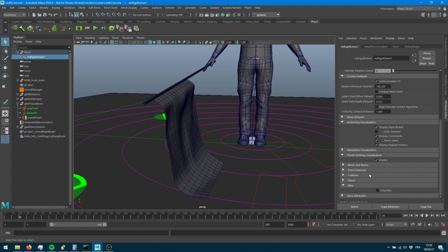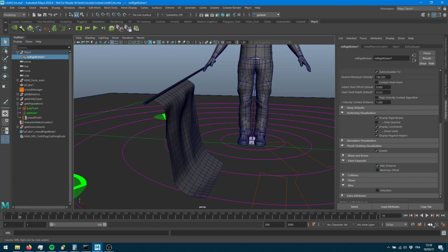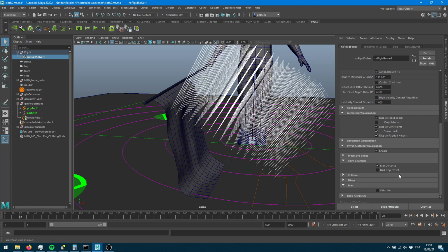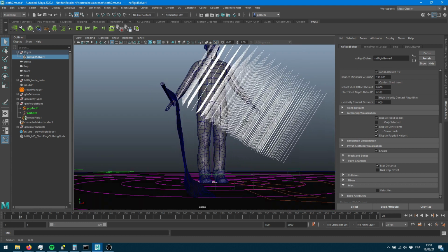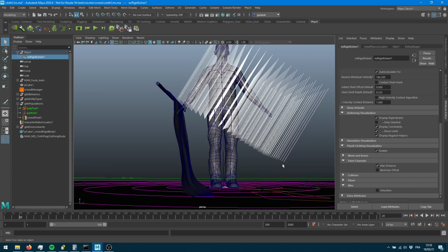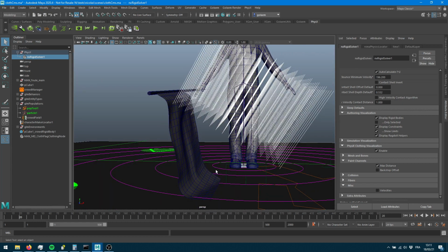I can actually show what the max distance is here. I can ask my system what my maximum distance per vertex is, and from what I can tell, the distance between this point, which is the original point, and that point is probably superior to that value. This is why we feel blocked by our unit here. So if you don't really care about how much distance your vertex can go through, I'd recommend painting a pretty high value so you don't feel limited.